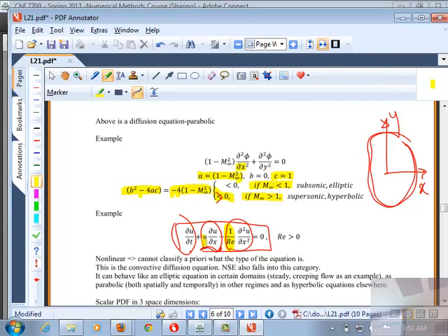If the Reynolds number is very small, and if you have no transient effects, then it's essentially an elliptic problem. But if the Reynolds number is high, that is, the convective term is high, then it can behave like a hyperbolic equation or a parabolic equation. Waves, for example, are all hyperbolic phenomena. So it's very difficult. So this classification is only good for us to launch in the right direction for developing numerical algorithms.